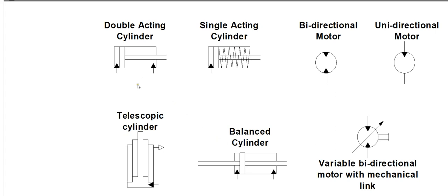Whereas if we go back up to this double acting cylinder, this cylinder could also be called an unbalanced cylinder because it has a larger surface area on the bottom than on the top when we're looking at surface area of the piston, because the rod is taking up some surface area. So there's an imbalance or an unbalanced volume on either side as well. So this would be a balanced cylinder. Cylinders like the two examples up here would be unbalanced cylinders.